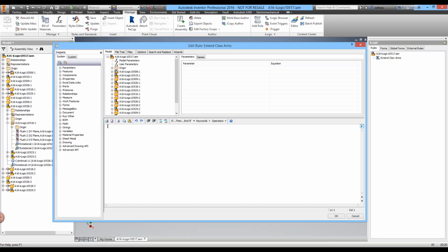All right, so let's start to create our iLogic here. What we wanted to do is create what's called a select case. We could actually do an if then end if. So if expression, then do something. That's how this reads. Else if, you may have another condition and it does something else. Else is to capture all other options.